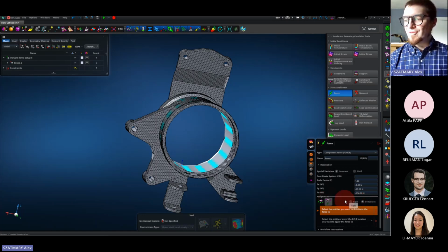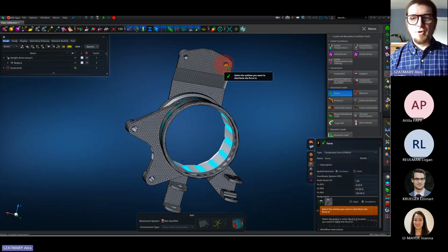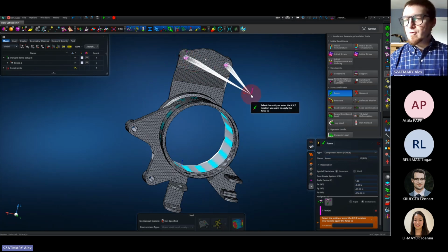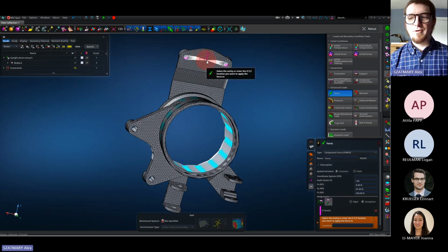In Apex, the term for this kind of thing is called discrete ties. In Nastran, it's called a rigid body element, or RBE2. So RBE2 or RBE3 is what we're dealing with. We're doing RBE3s. I'm going to click on this hole and now click the middle mouse button. So Apex is trying to generate an RBE3. It's saying I'm going to put the loads onto the nodes inside of those bolt holes. But where's the force going to be applied? Well, let's try and get it to the centroid of those two bolt holes.